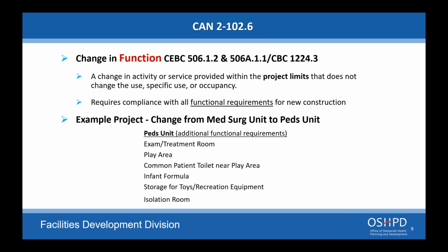Before we were talking about equipment replacement, not triggering accessibility. This would trigger accessibility. This would trigger compliance with the fire alarm system. So if you have an old fire alarm system in the building and that's what's being served, and you're doing accessibility upgrades, there may be an alternate method of compliance required to keep the existing fire alarm system. The intent is not to make you replace an entire fire alarm system because you're upgrading one room. So I would definitely, again, make a phone call and talk to your region supervisor.